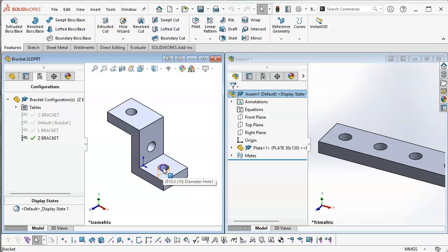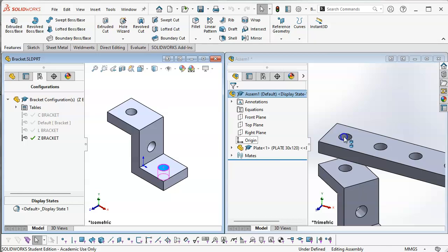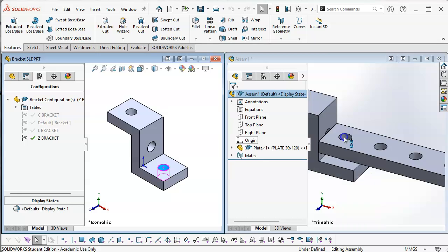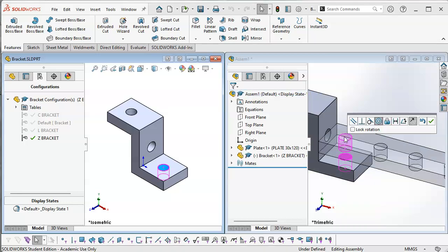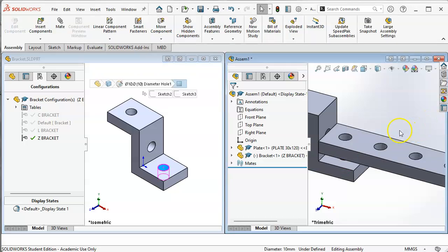So we're going to go to mate references on the next, but this will be an introduction to mate references, that when I grab the cylinder and I drag it to another cylinder, and there's a little bit of finger contortionist type stuff here, where as soon as I place the cylinders, I get the stack of marshmallows, or cylinder to cylinder concentric, and then I can hit tab to flip the mate alignment. And when I let go, I have the concentric mate. I don't want to lock the rotation, but I could. And we'll go ahead and hit accept.